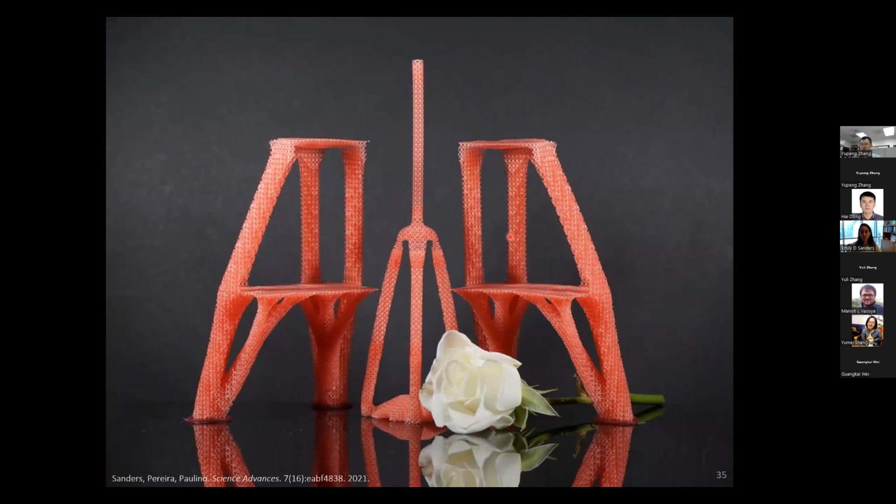Okay, so what I did here is I sliced my part for a printer twice as big as my 3D printer. And then I divided those slices in pieces and sent them to the printer individually, and then assembled the part afterwards. And what this means is, because of our voxel-based approach, right, we can arbitrarily scale the macrostructure geometry as large as we want and keep the meso-scale features at the resolution of the 3D printer and essentially achieve a really large separation of length scales, of course, given an appropriate manufacturing platform, okay?